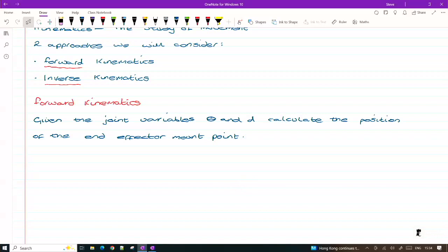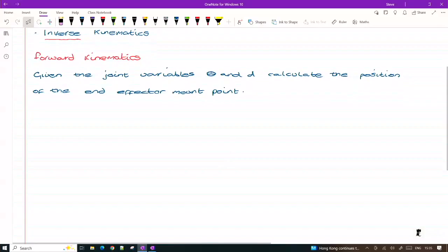So I'll just pick up on that point about the control side of things. The other approach is inverse kinematics, where we pick a point and calculate how the robot should configure itself. What we can do is, once we've positioned the robot where we want it, we can then backtrack, we can do the forward kinematics and make sure all the angles are set to where they should be, because you'll have feedback, you'll have sensors within the joints that tell you where they're positioned. And based on the errors inherent within your robot structure, you can make very small adjustments as well, using both. And again, I'll pick that up again.